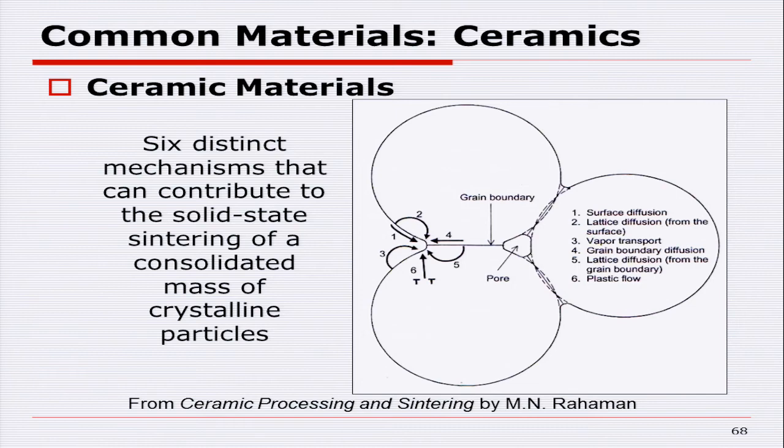Well, you do that with some of the stuff that you want to put on the outside of your pots as well. You have these different slips, and they have a lower melting point, so that when you put them on and you refire that pot again, the pot doesn't melt. Understand, if the pot melted, it would just collapse inside your kiln. It would lose all its shape, its structure. You don't want that. You want it to keep its shape, but yet you want an exterior that is fairly impermeable.